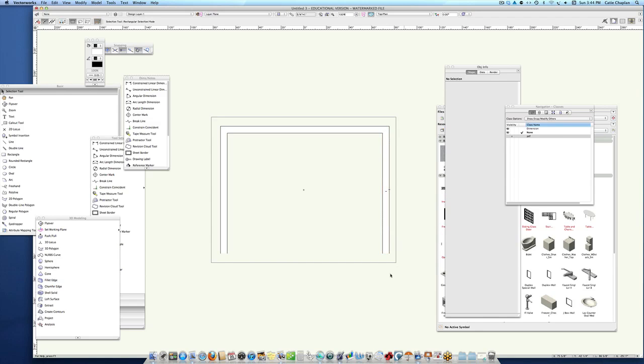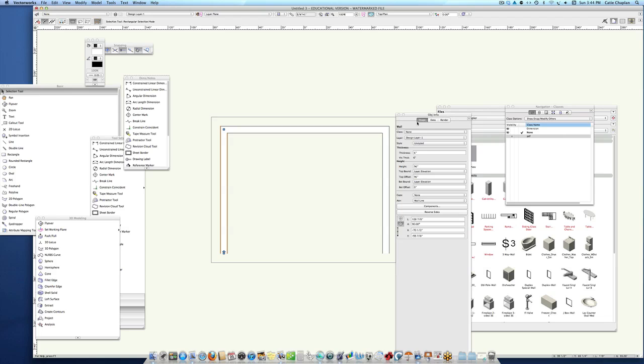So I have my walls here, and they're kind of open there. It probably doesn't matter a huge amount for what we're doing, but if we wanted to frame this, there wouldn't be any kind of end stud there. So what I can do is select the segment of wall, and here's this thing called caps. So I can cap the start or the end, and the start has the little arrow, and we had no control over which was the start and the end.